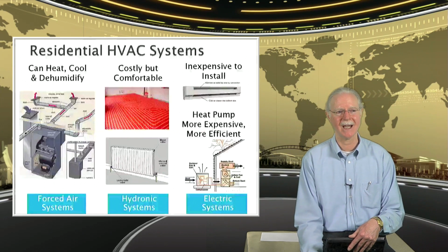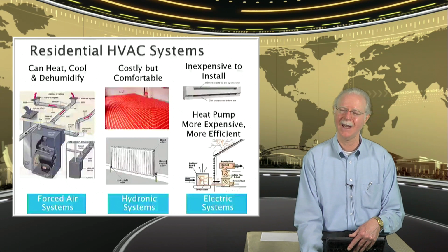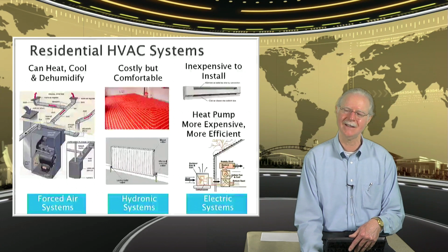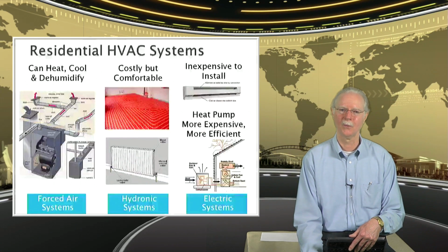So they have thermostats that actually track the history of outside and inside temperatures over the most recent past, and it adjusts the heat up process so that the heating doesn't take place right at the coldest point in the day. There's probably still some penalty because it's a heat pump, but the control system makes it so that the penalty is much less.